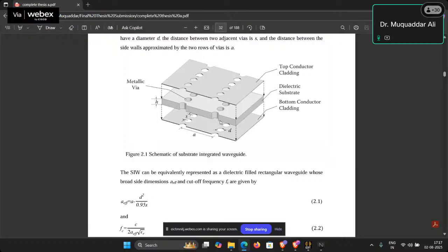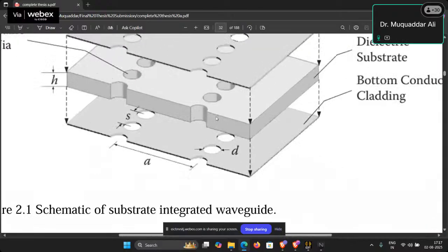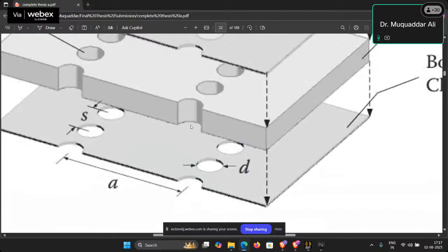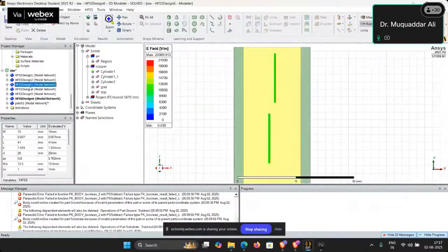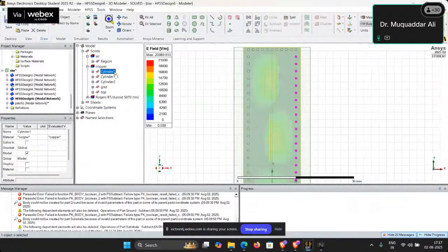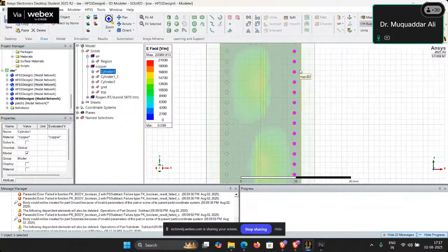Through hole plating, in which on the walls only the metal will be coated. So that will remain hollow, but the side wall has been realized by through hole plating, so it now has a very thin layer of conductive material. These holes have a very thin layer of conductive material, and in our simulations, you can see these are the complete cylinders.